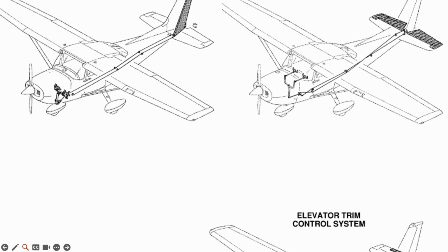So both of these, just like the ailerons we talked about, are controlled with cables and pulleys. I forgot to mention the rudder is attached to foot pedals. So instead of a gas and brake like you have in the car, you have 2 foot pedals, and those have 2 functions. One of those is to control the rudder. So if you do kind of a sliding motion with your heels, that's going to deflect the rudder like that. And the other function is if you depress the toes, that's going to activate the brakes that are on these back wheels. And we'll talk about those more in a second.